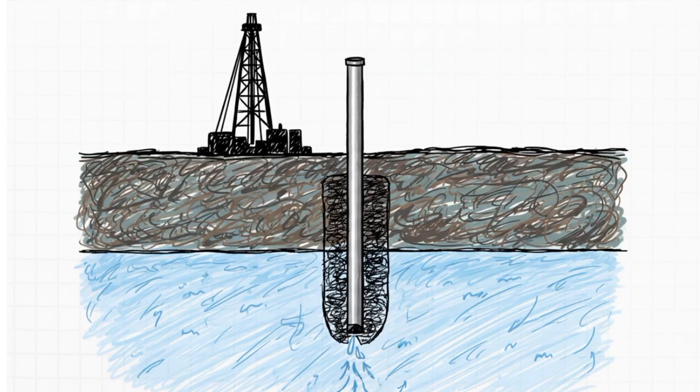Based entirely on those electrical readings, their final engineering solution was brilliantly precise. They recommended drilling a massive test borehole down to 1,000 to 1,200 feet just to reach that cleaner lower aquifer. But, and this is absolutely crucial, to prevent that nasty, highly saline water from the upper aquifer from pouring down and ruining the well, they mandated that the borehole be sealed with bentonite clay all the way up to a depth of 600 feet. The survey didn't just find the water, it dictated the exact engineering required to protect it.